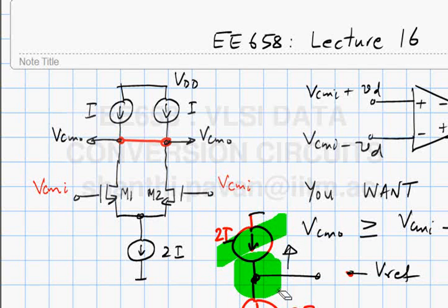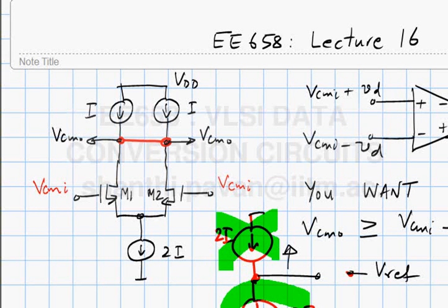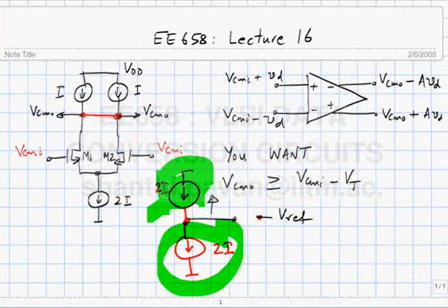So if you want to make this current source exactly equal to this current source, what you need is a tunable current source, and this is what you would pretty much do in the lab, right? You make this current source fight against the pull down current source, keep monitoring the potential of that node and go on tweaking the control knob on the top current source such that the potential at the junction stays constant.